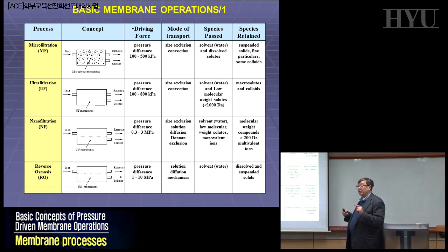In ultrafiltration, you are starting to have asymmetric membranes. That means you have membranes in which the thickness is always 100, 200 microns, but the support is 99% very porous, while on the surface there is a thin layer, still not dense, but much less porous. The size of the pore there is much smaller than the one you have in the rest. So these are asymmetric membranes. That is good, because in this way you can minimize fouling inside the pore. Basically nothing enters the pore except the species that can go easily across.